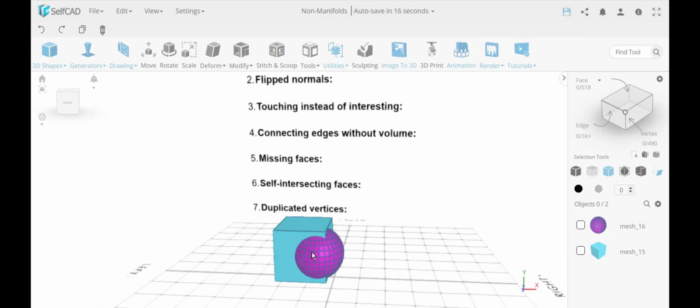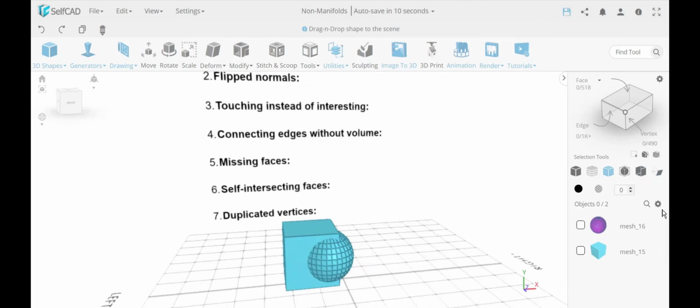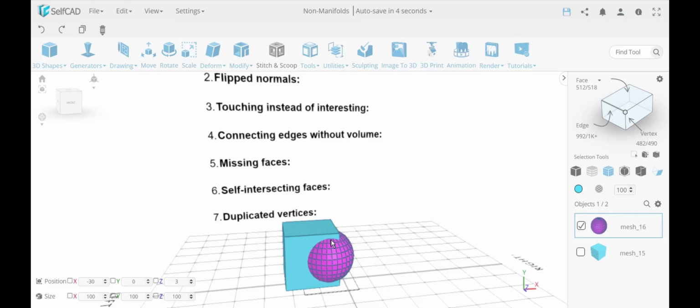So how do I handle normals? First off, you have a tool over here, now you see I can change it to no coloring. You wouldn't even know something is wrong. And if you turn on backface coloring, you can see something is wrong. And if you see something misbehaves, then many times the problem is with flip normals. As you see later, this can also detect other things like self-intersections, which we'll see later on number 6.